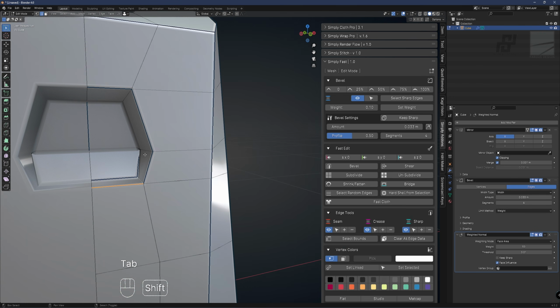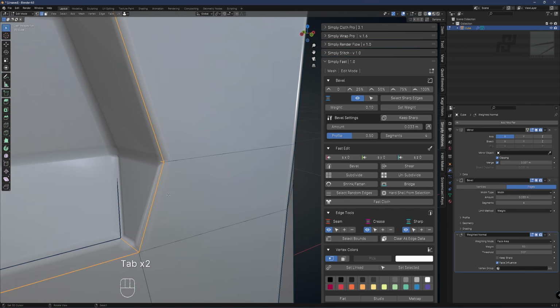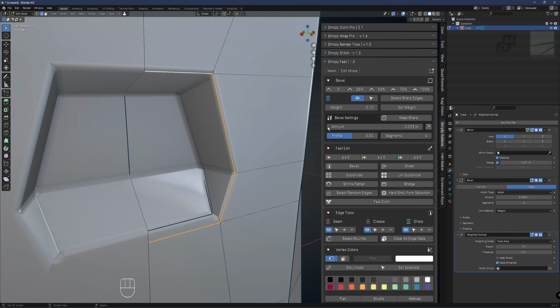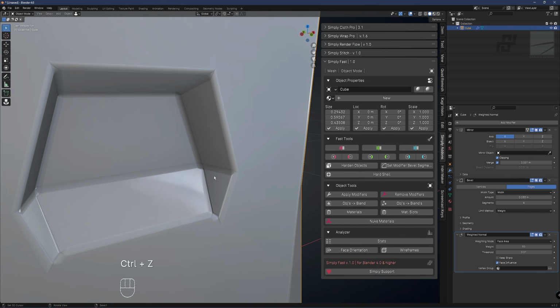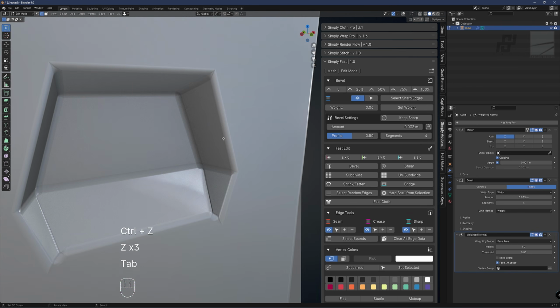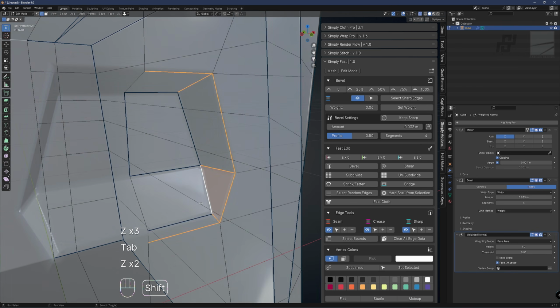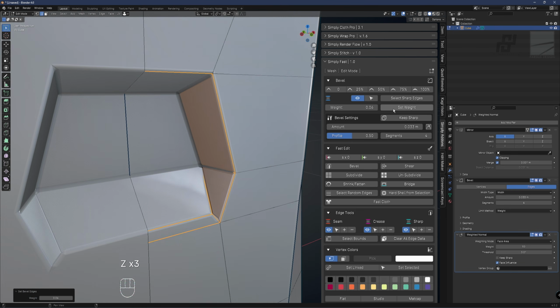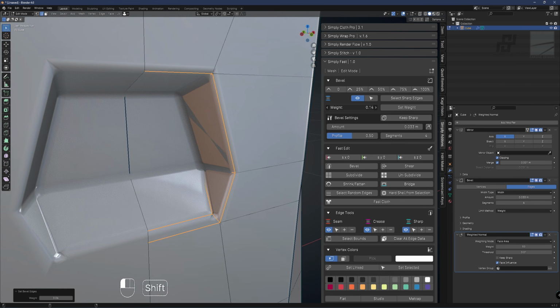So we can check the shading and it looks great. But here and there I don't like the shading, so I check again. There it is. So in this case I would recommend to make it lower size. We can set it like here. Lower size, so we don't have these intersection issues.